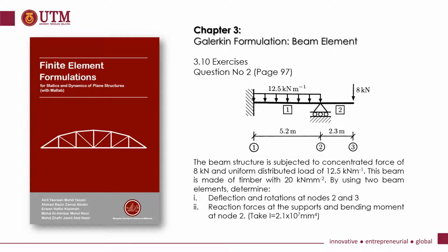So what the question wants us to determine is the deflection and rotations at nodes 2 and 3, as well as the reaction forces at the supports and the bending moment at node 2.